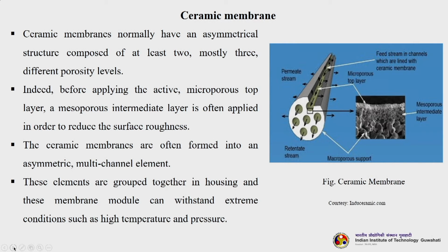Now, in this particular figure, you can see a ceramic membrane. You can see it is a tubular type of structure here. So, you are seeing so many holes here. Actually, these are your membranes, and these are the lumens through which your feed will flow. So, feed is flowing, you can see the fluid is flowing here, and the permeate is out from the overall membrane structure. If you consider a pen, you can imagine there are holes here through which the feed will flow and the permeate will come from the outside of this membrane, from all across the membrane, all the surface area.